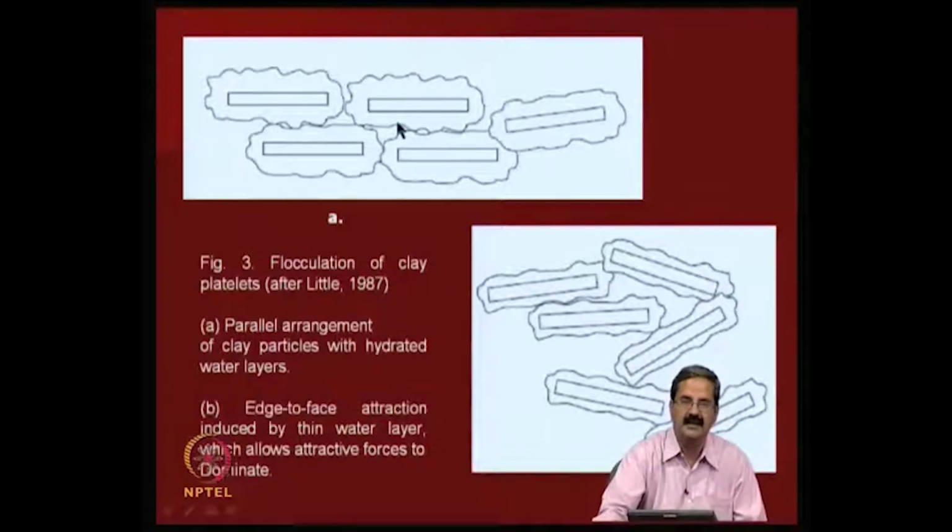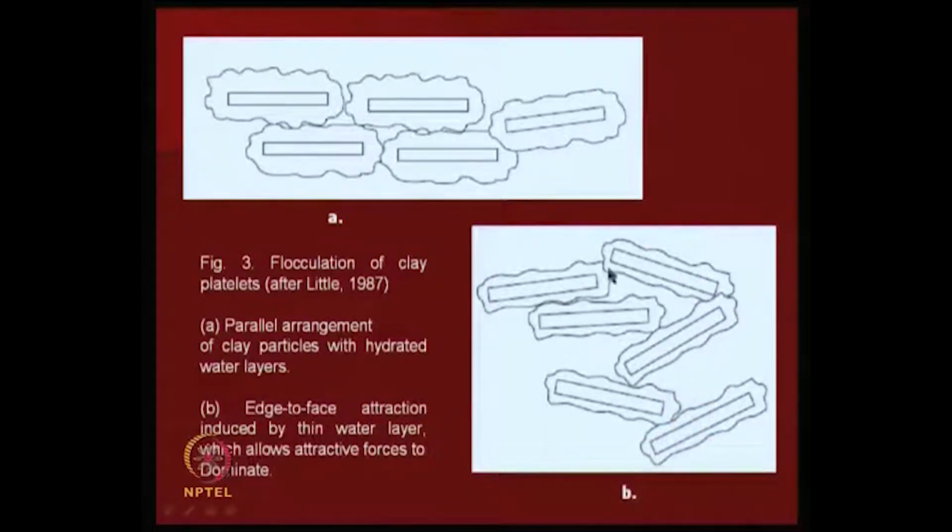But then for the same sodium bentonite, when you add a bit of calcium or saturate with calcium, what happens? It has a formation of the edges like this, wherein you will see that edge to face flocculation occurs.